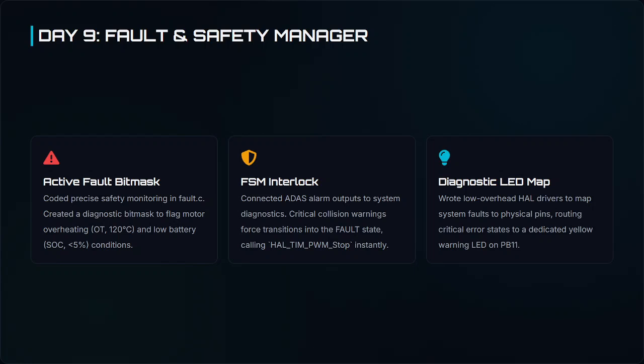To monitor safety critical parameters, the system continuously evaluates motor temperature against a 120 degrees Celsius thermal limit, battery charge against a 5% low voltage cutoff, and the ADAS line for critical collision warning.